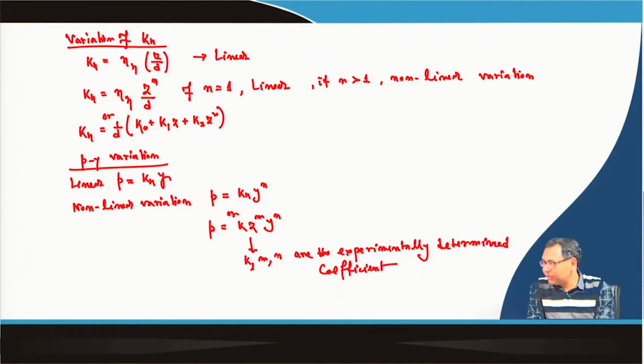The first one is the linear variation, the second is the non-linear variation. So, that means the beams are not only resting on the linear spring, they can be resting on the non-linear spring also. That means you can incorporate the non-linearity in the load deformation behavior.